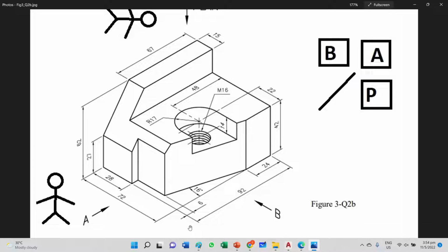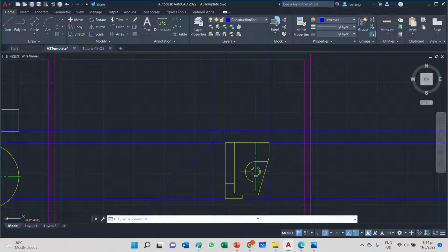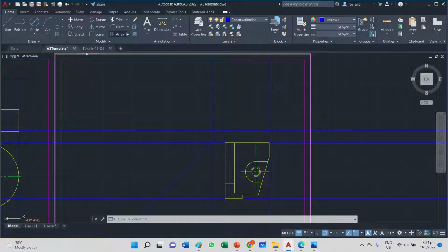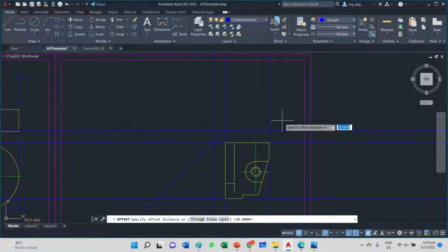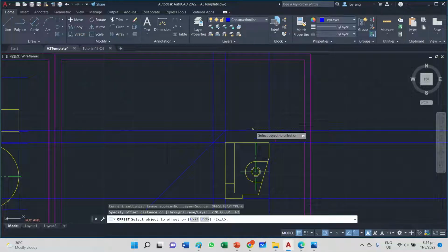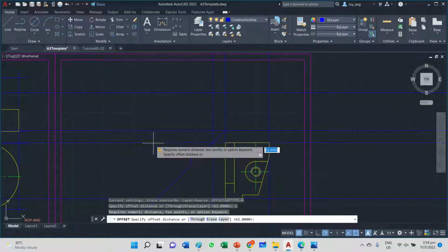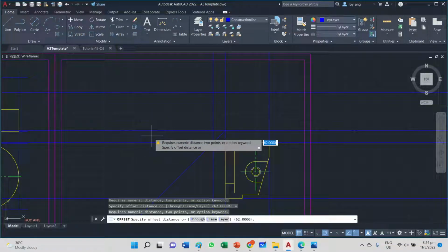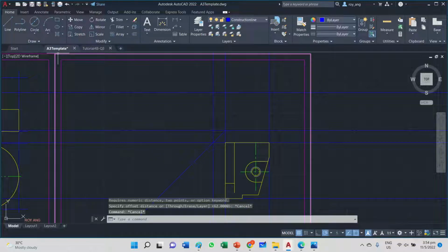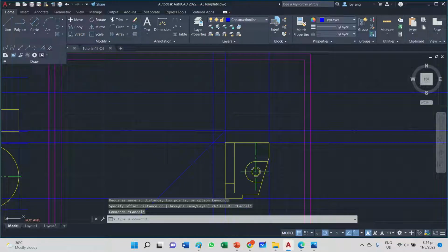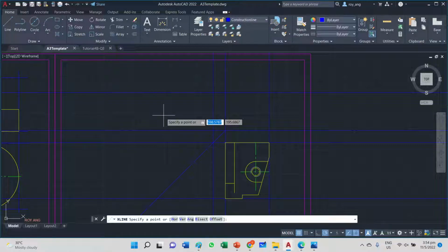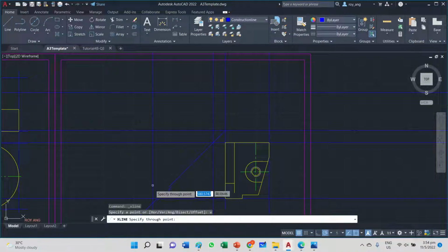The front view is here. That point is where I'm going to do an offset. And from the plan view, the point is here. So I project it across, and I go up. Hence this intersection point is the end point of where the hexagon is going to be. Then it goes down to close this segment, and that's part of the hexagon.